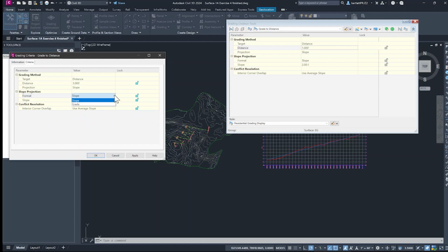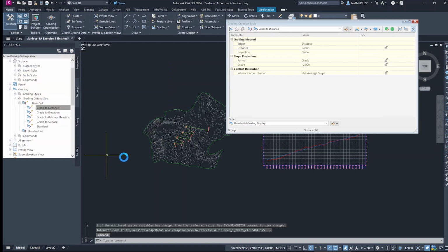We're going to use that as a grade, and I've told you in the instructions for this assignment that for the Hogle Zoo trail we're going to do that at -2% crown or slope to the side. So I'll put that in and hit OK.